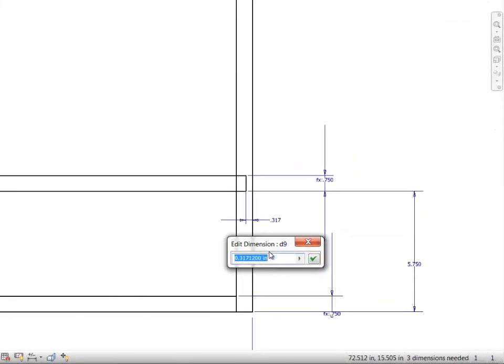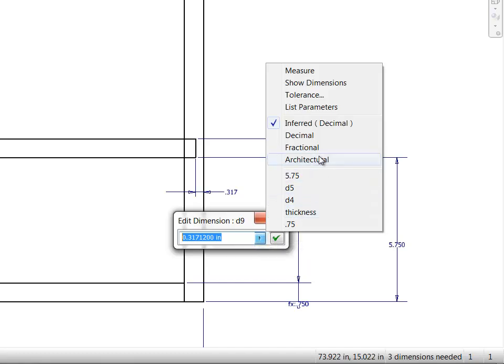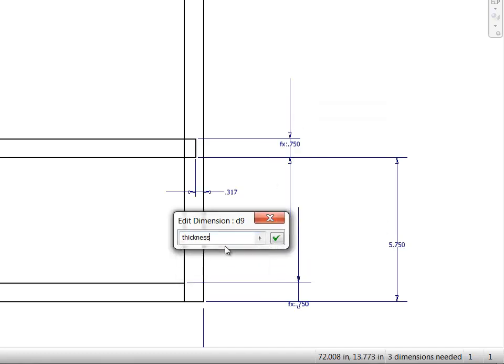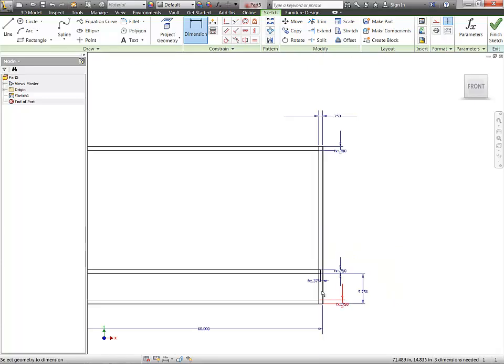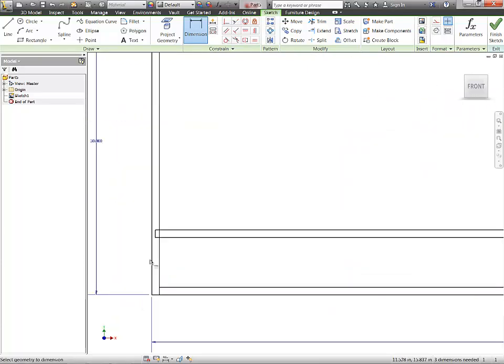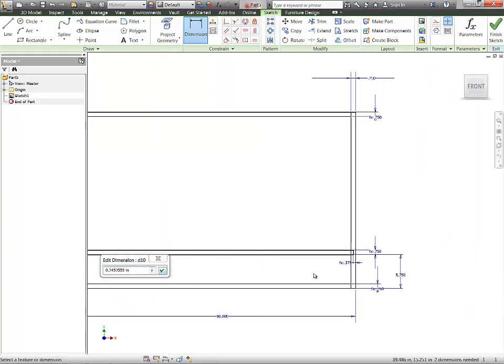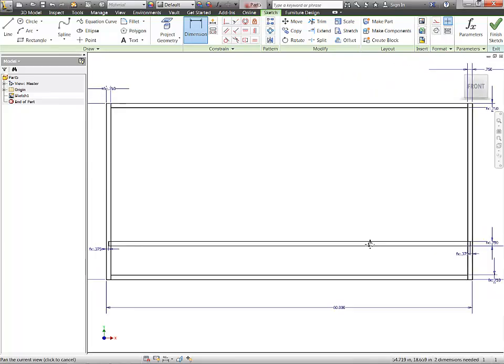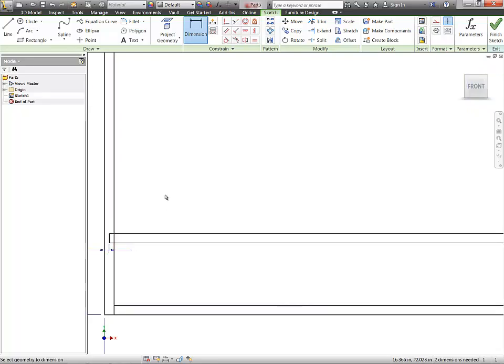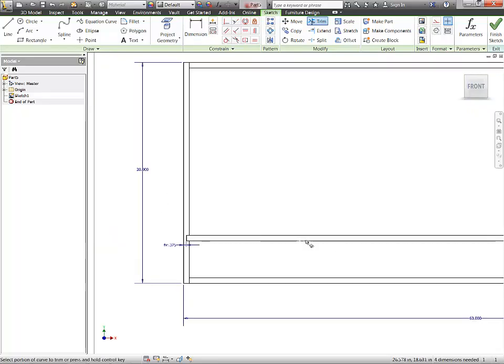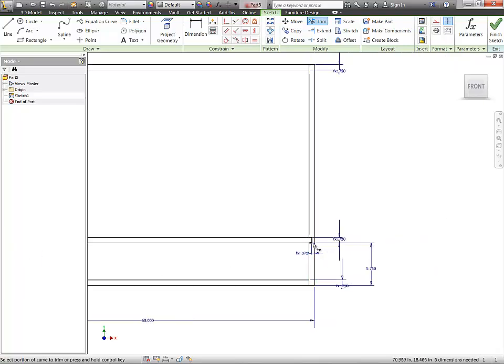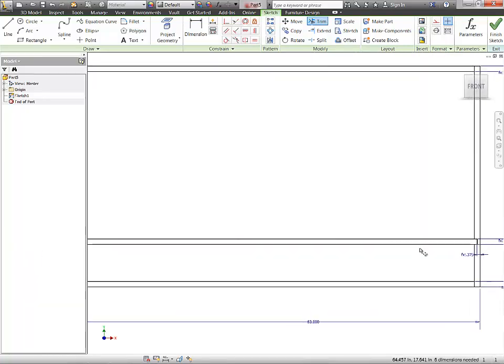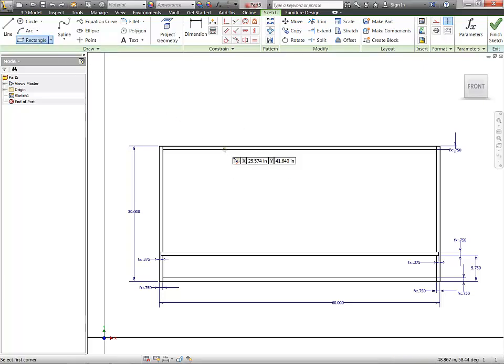What I'm now also doing is I'm going to say the depth of the dado is going to equal the thickness divided by 2. Thusly, no matter how thick the sidewalls become, the dado will always be half of the depth of cut. Again, planning for the future, this could be a prototype item that I use over and over again, and it gives me the ability to quickly just change a couple dimensions and get end results. Trim up what I don't want, basically creating my dado, making sure all my constraints and dimensions are there, and we move on.